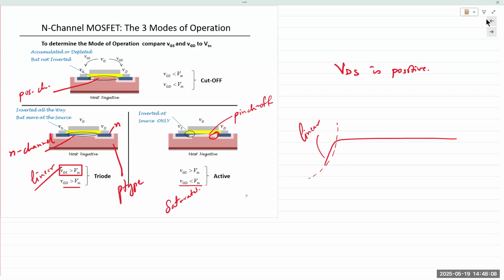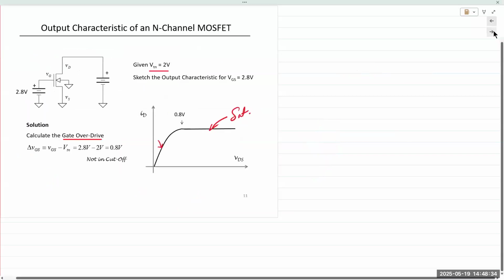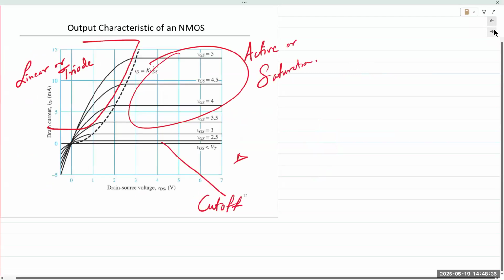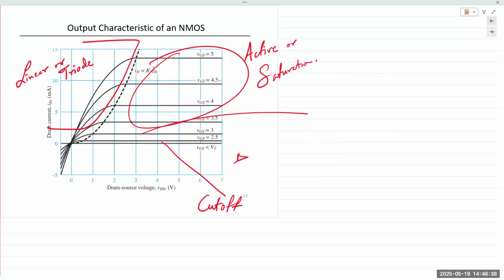What happens, in fact, is that there is a small gap left where the electrons are now flowing at a constant rate. They are now injected into the depletion region. And because there is a large electric field, they are swept through the drain terminal. This flow of electrons remains at a near constant level. And this is verified by the fact that the drain current, ID, flattens out.